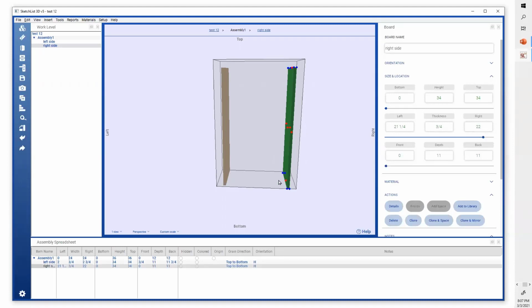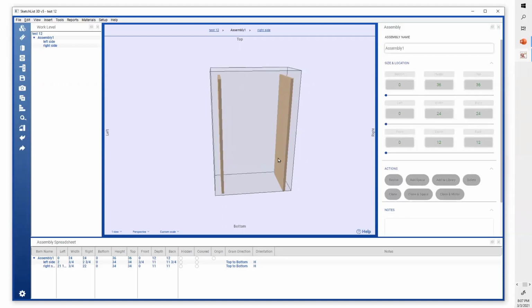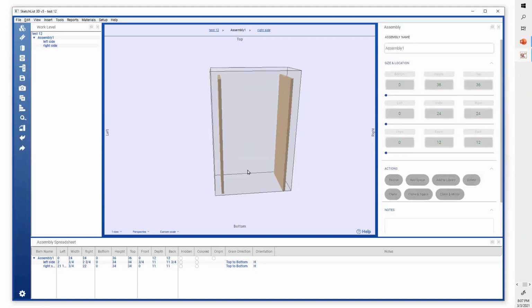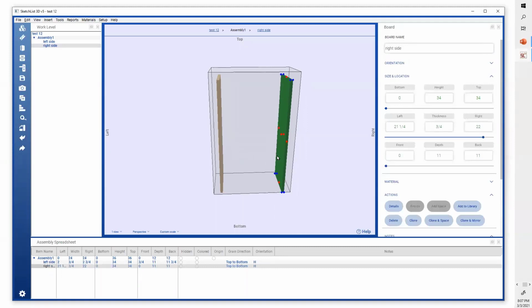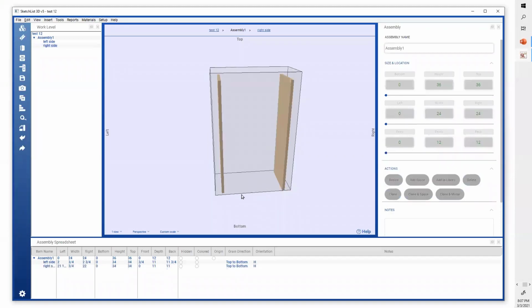And this is 22, which is what I wanted. So that's just something that you kind of want to know, is that it's always from the left of the container. I think sometimes people think that whatever that distance is, 21, is that between those two boards. It's not. Everything is referenced to the point where left, bottom, and front are all equal to 0.